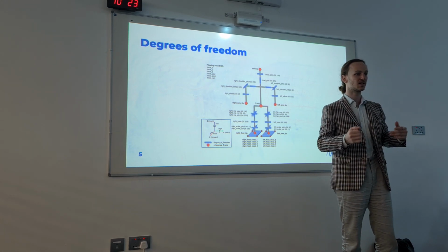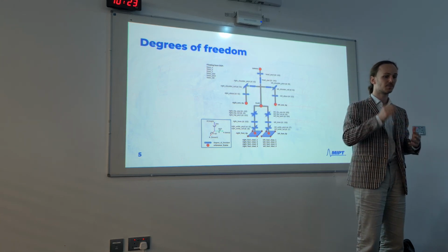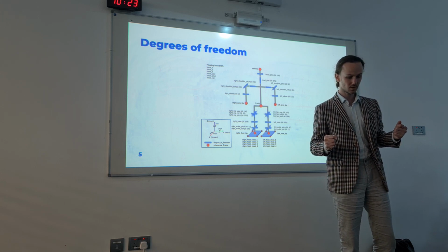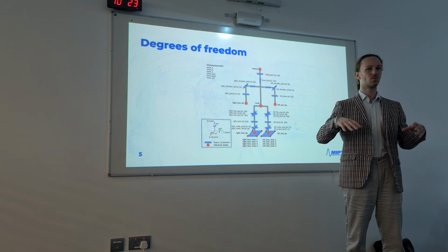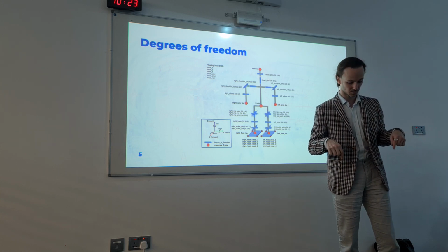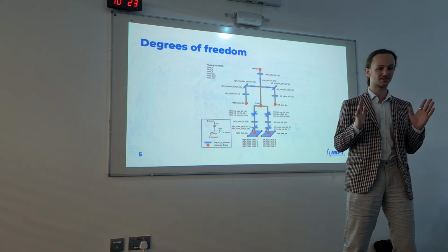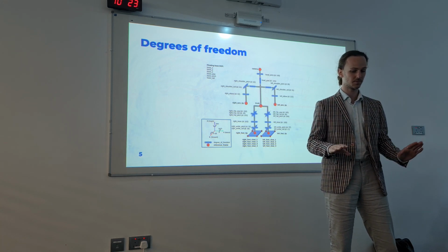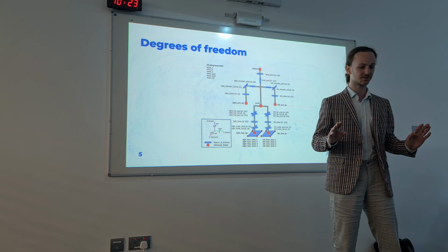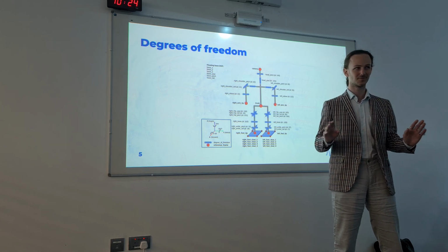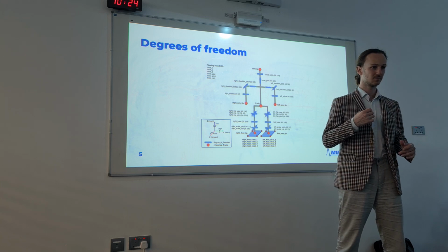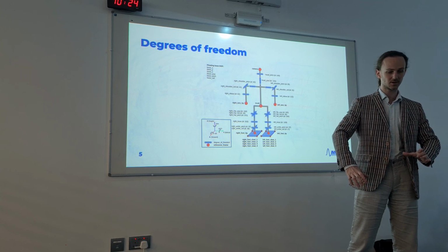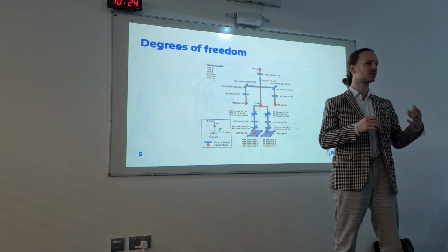You actually have to be capable of solving the inverse kinematics problem. We want to first be able to walk. And the second, while standing, so while the feet are fixed to the surface, we have to be able to move the center of mass, like I do now. I do not move my feet on the ground, but still there is a certain bounding box, or I should say support polygon. So if we project my center of mass on the surface, there will be a certain polygon in which the center of mass could be, so that I'm not falling.